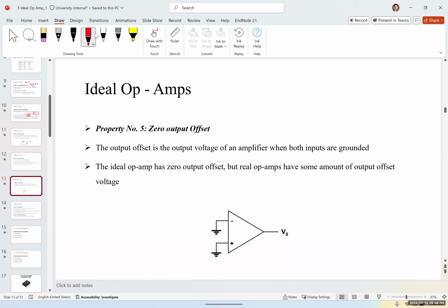And what we did in an op-amp, we have the DC offset voltage cancellation pins number 1 and 5 that I showed you, that you connected with a resistor to the power supply and cancel that DC offset voltage.